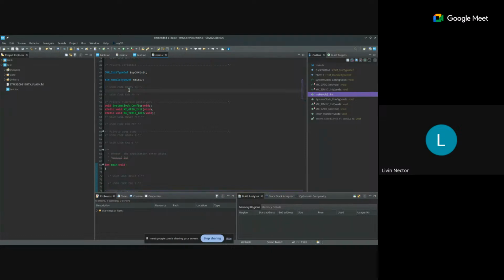So why is that necessary? It is because if we are using CubeMX, what happens is when you change a configuration, the code outside of these comments gets overwritten. So that's why you need the sections to write HAL code with the STM, right? Whatever code is outside of these comments will be overwritten if you change this .ioc.